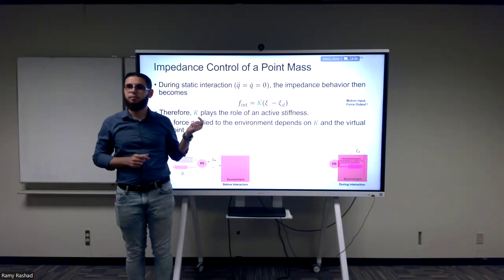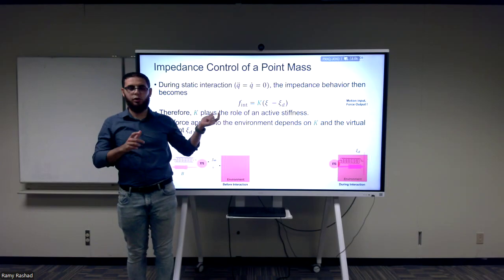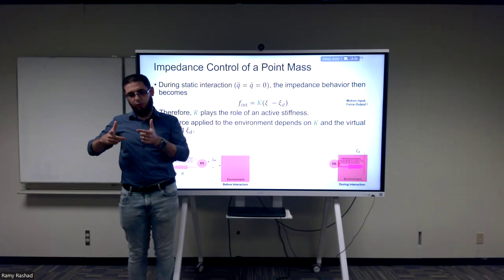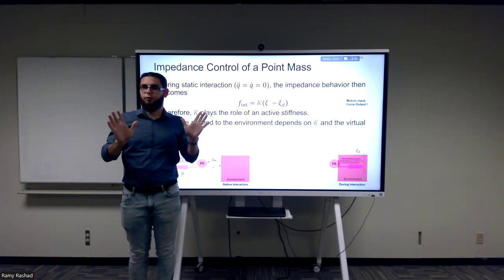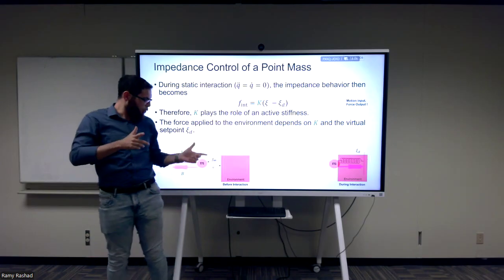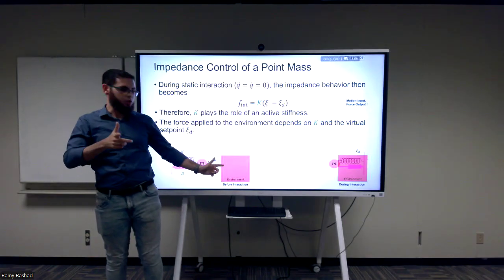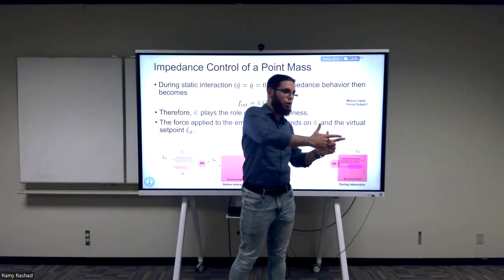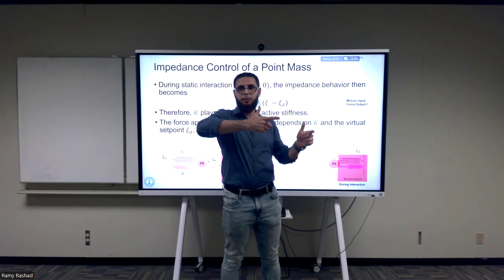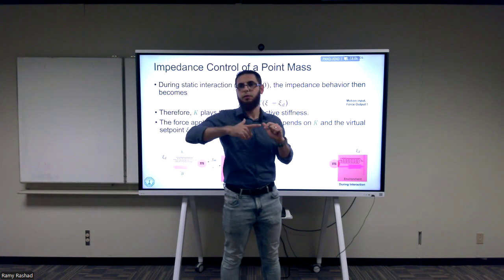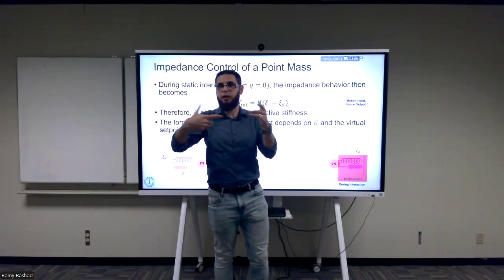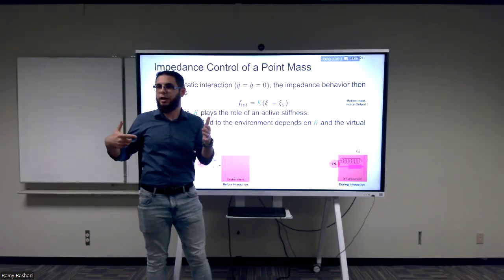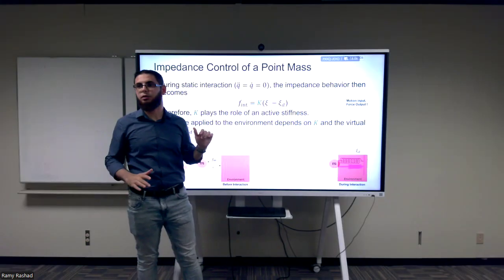How we are doing the impedance control, we want to reduce and avoid the impact of the force. Impact. So you're saying that if we're moving very fast, then there's an impact. Forget about impact. Let's say that we approach the wall very slowly until we reach that point, and then I start to move this also very slowly. You see, I'm going to be applying more force to the environment. So even if there are no impacts in terms of a large momentum exchange, we still have this interaction force.